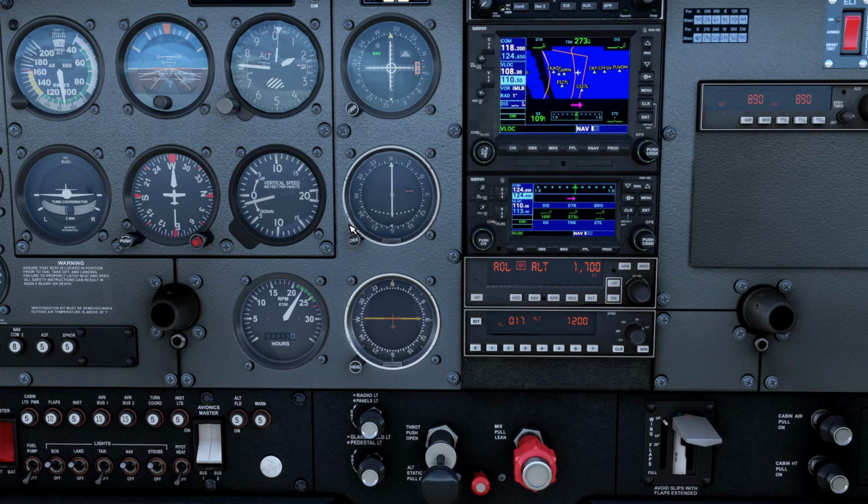But for flying a back course approach, I don't recommend using the back course mode. It's kind of all over the place and seems to not really track it very well. So an alternative technique for flying a back course approach is just to do it in heading mode, and then use the heading to keep yourself on the back course approach course. You activate this mode by pressing the back course approach mode selector, which is the REV button. Not sure why it doesn't say BC like every other back course approach button in the world, but it doesn't.